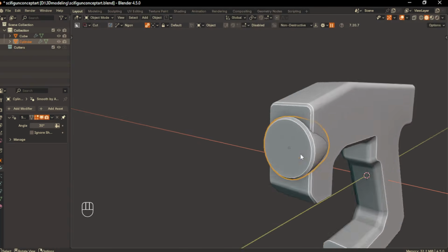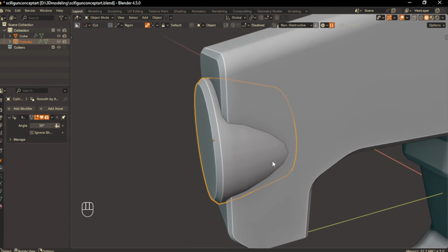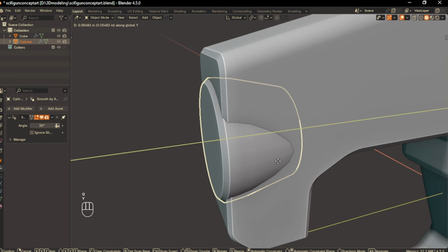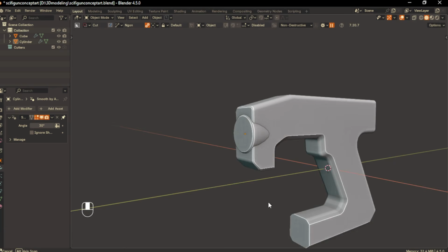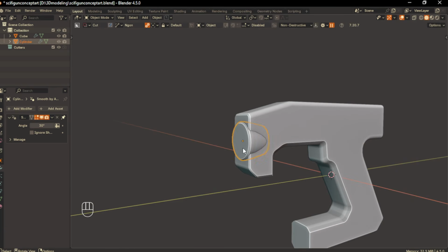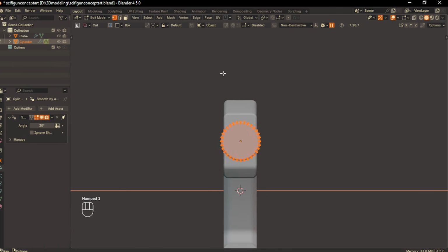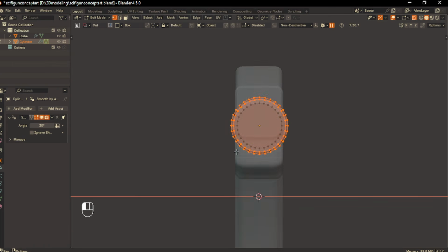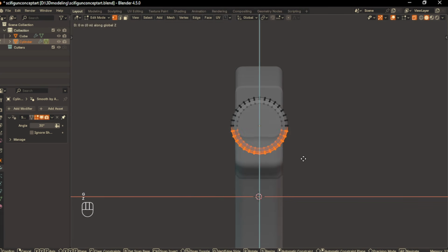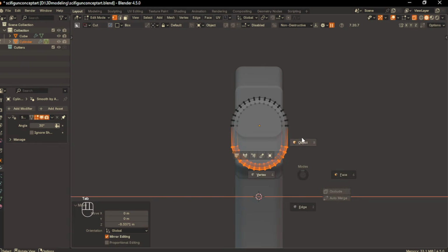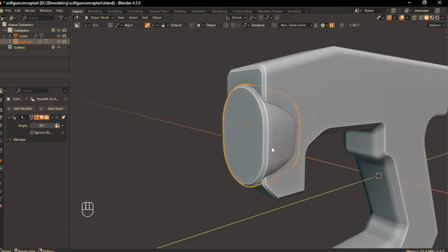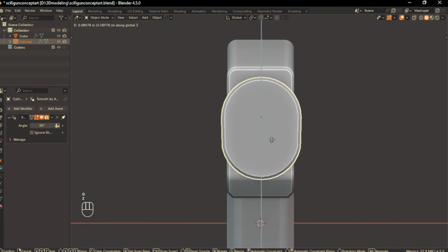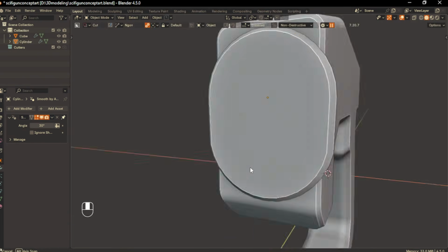Looks solid. Now I'll push this cylinder in a little further until it blends nicely with the main body. Just connecting those chamfers together. Let's hop into vertex mode. I'll enable X-rays so I can grab through. Deselect the extras and box select the spot I want. Move them down a bit on the Z. That's an interesting shape. Let's nudge it up slightly for symmetry, and yeah, nice balance now.